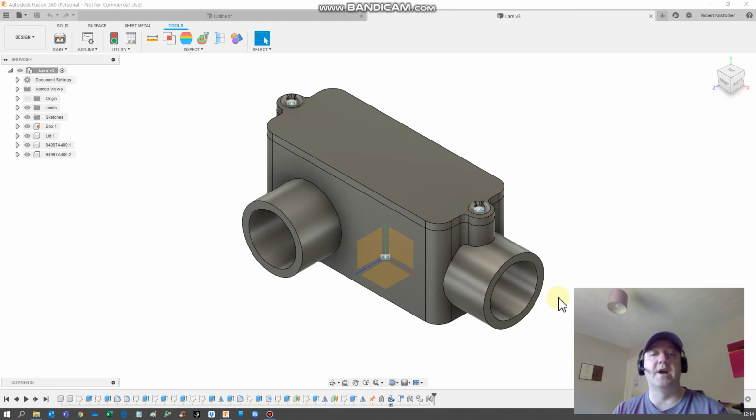You don't print it directly from Fusion. You send it to Cura, and Cura turns the 3D model part into a part that can be printed, because the way you print something is it's not solid. It won't have a solid internal. It'll have structure in it to support it, but it's just the way you turn your solid model into a model that can be printed.